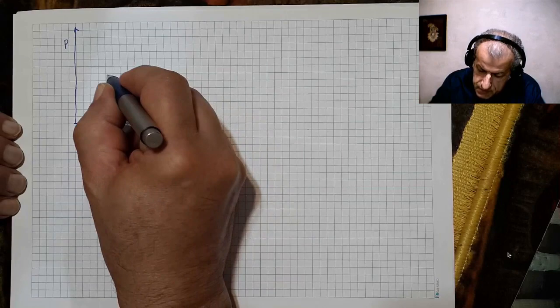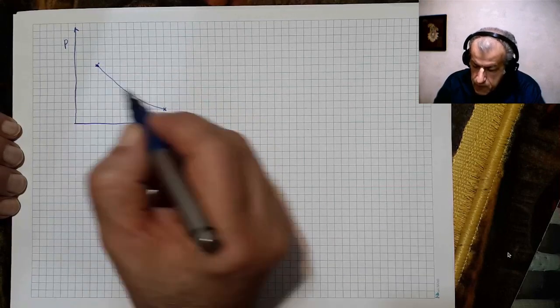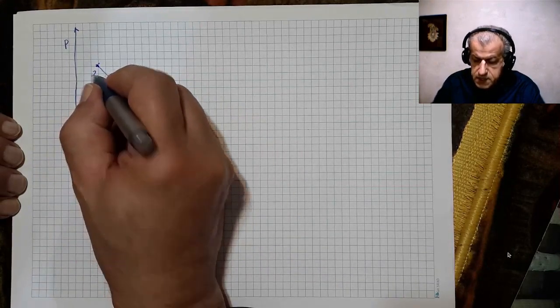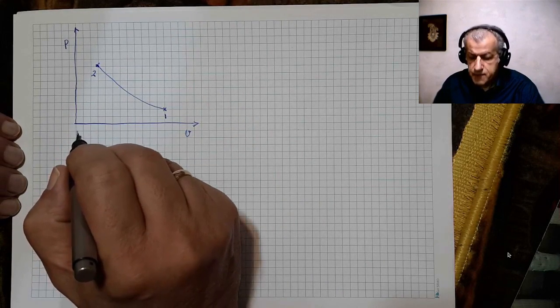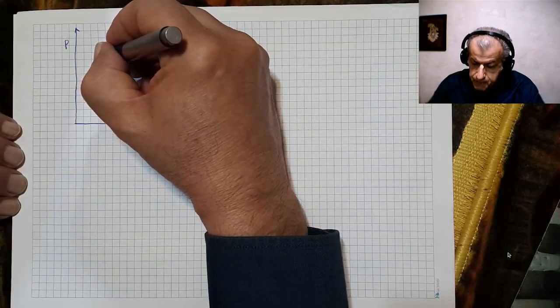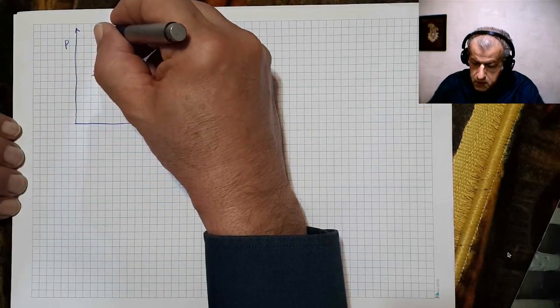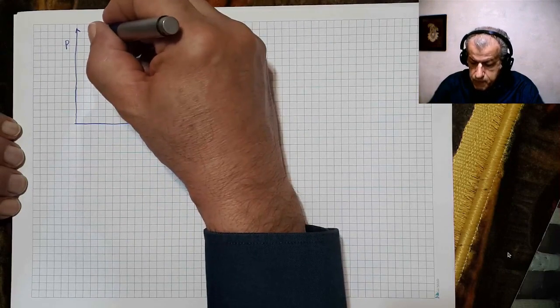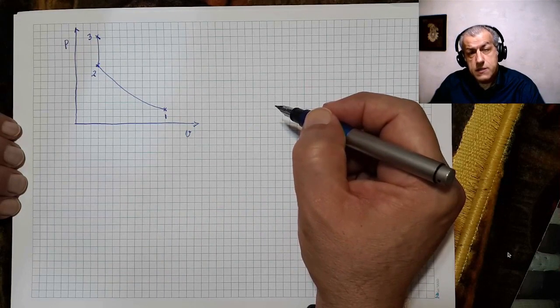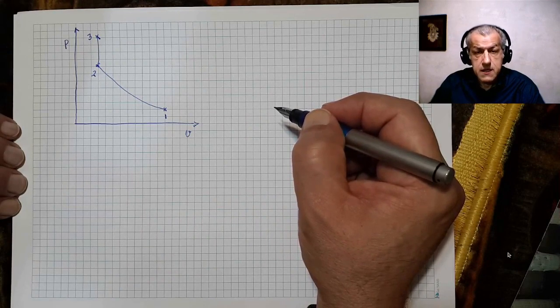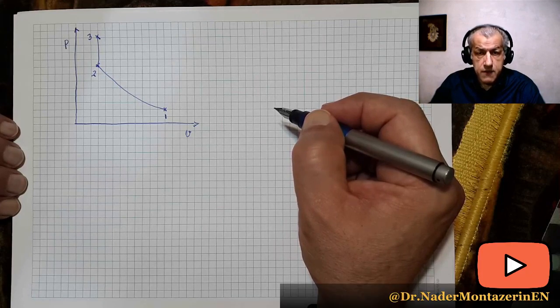And there is an adiabatic and reversible process in the ideal dual cycle, which brings it to 2, the compression part of the cycle. Then there is the constant volume part, which is where in an Otto cycle heat is added, and in a real gasoline engine is where the spark acts and the fuel starts to burn.